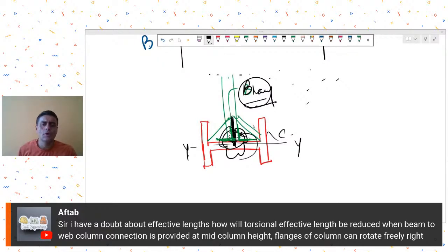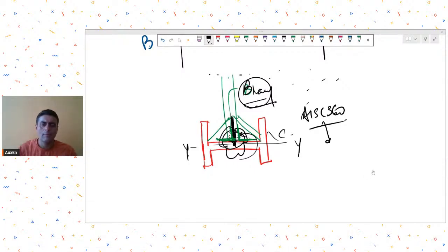Over there this problem is seen, and AISC 360 tries to address this issue and tells you that if you have bracing systems, they may not be able to provide you torsional restraint. They may, however, provide restraint against flexural buckling, but not torsional restraint. So this statement is there in AISC 360, and accordingly you have to take higher lengths for torsional buckling.